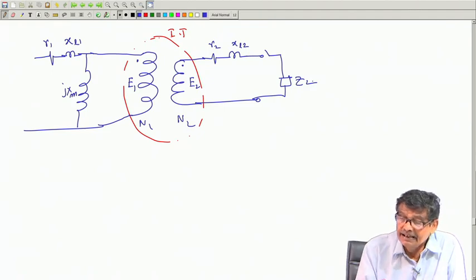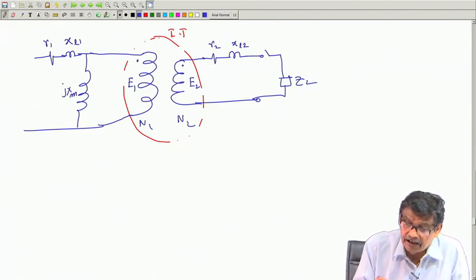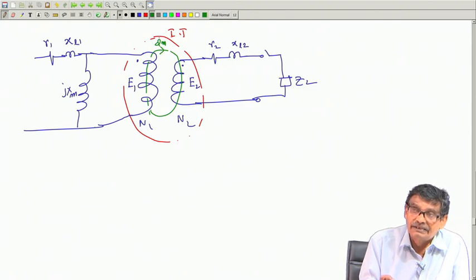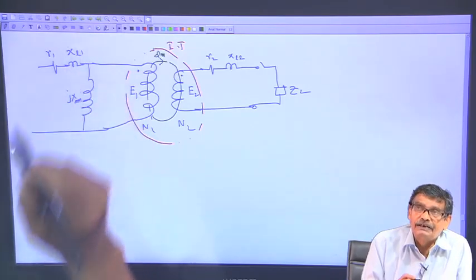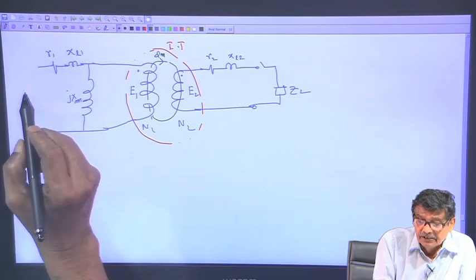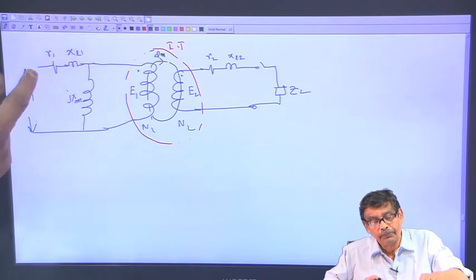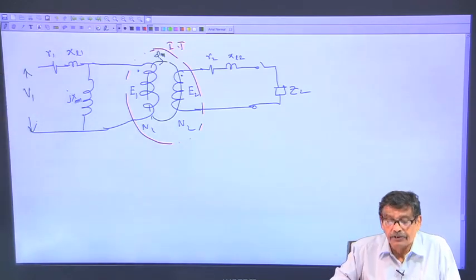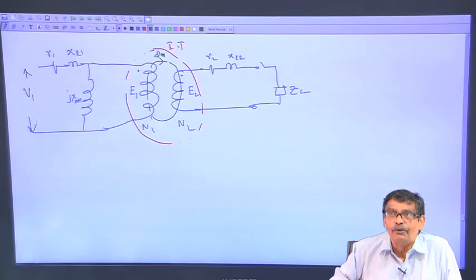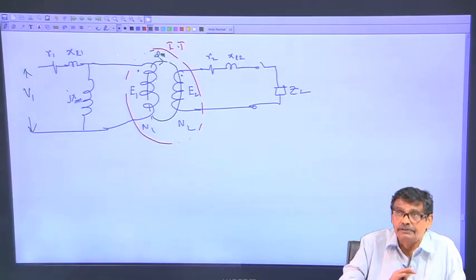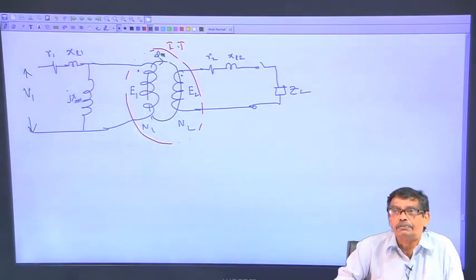Therefore, this is the ideal transformer, here all the fluxes are mutual, mind you. Here it is phi m, the mutual flux, plus phi L1, the leakage flux, N1 d phi L1 by dt, shown as a drop here, because this is your supply voltage. Now, we know out of this total supply voltage a portion will be dropped in R1, absolutely no doubt, and there will be another small voltage drop because of leakage flux, which is not going to create your magnetizing current. No, that voltage is consumed by the leakage flux.